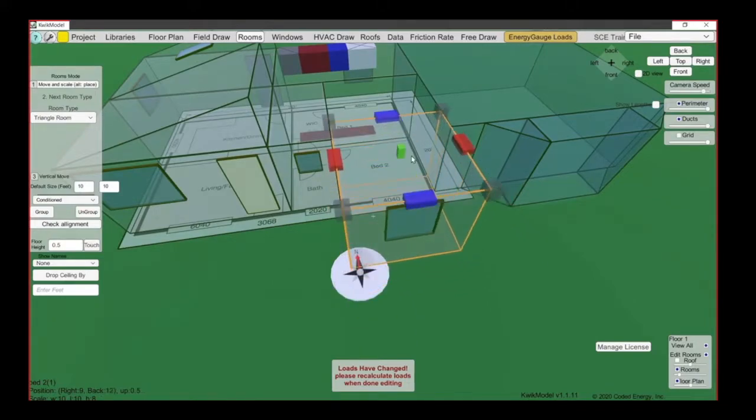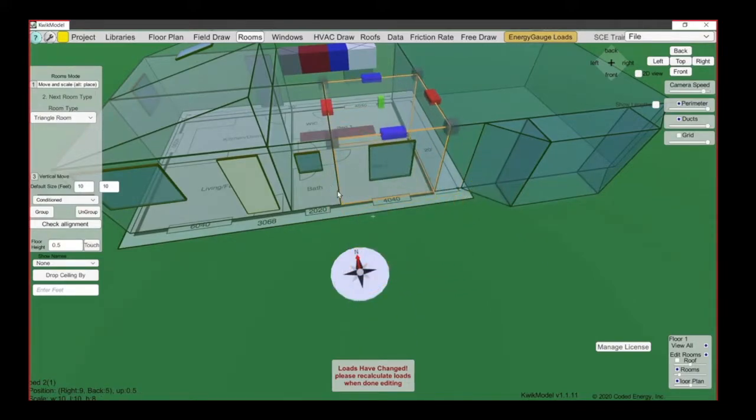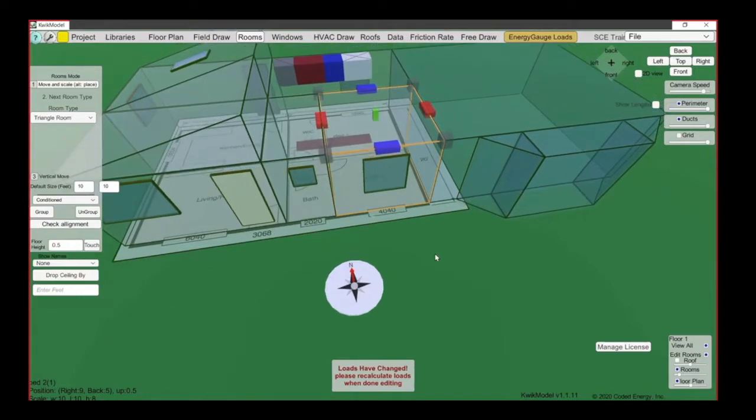But when I slide it back into place, the only exposed or exterior wall that it has is this front wall here and this window, and then the side wall here that's going to an unconditioned garage. This back wall back here, there's no heat transfer through there because that's another conditioned space on the other side. And Manual J assumes that the entire house is the same temperature. And when you have the same temperature on either side of a wall, there's no heat transfer through it. Okay? It's called an adiabatic surface.